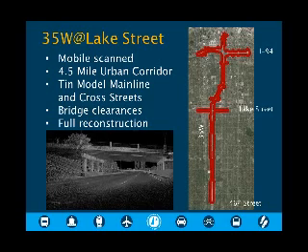MnDOT survey crews did all of the targeting for it and did the random shots that we wanted. And what we're waiting to get from them is a tin model of all the surface and also the bridge clearances through there, because we're going to be doing bypasses and some unbonded overlay on part of it and different things out there. So we needed to know where the surfaces were and also all of the bridges. So we're waiting for that to be delivered to us.